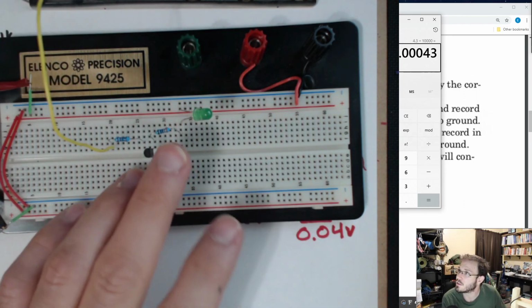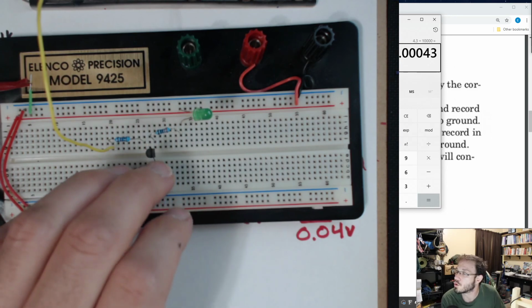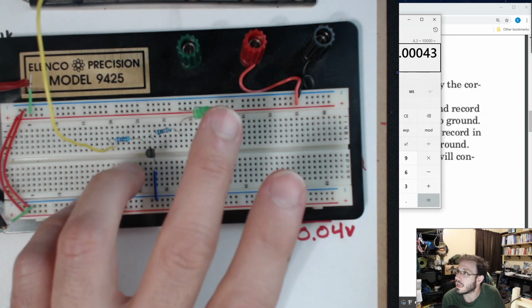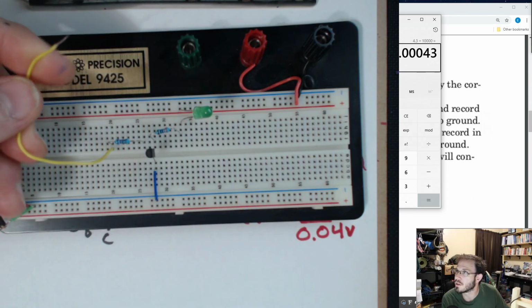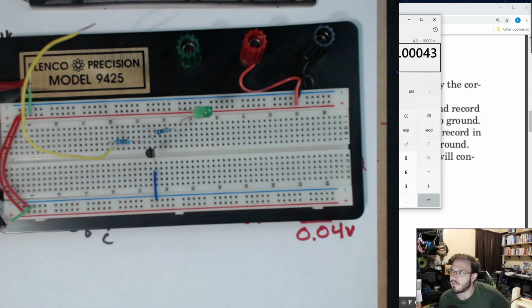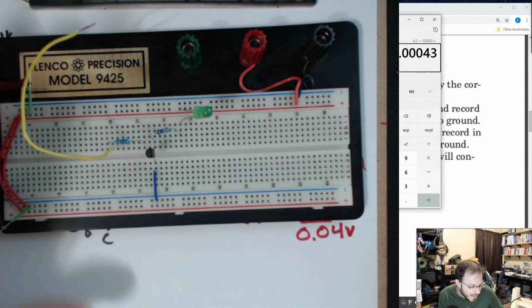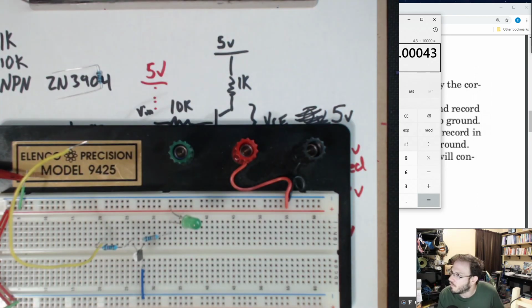So in this case, this transistor is behaving like our driver for the LED, such that we don't need to source that current from our digital devices. And this is incredibly convenient, powerful, and necessary to do in most embedded systems for most of your pins. Okay? So with that being said, that's it for the lab. You have your values recorded.